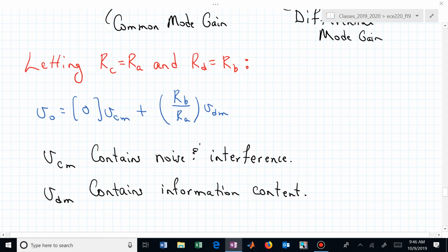The common mode, in general, if we had a sensor, or if you have been hooked up in the hospital, they may be measuring what your heart is doing. Well, you're picking up all sorts of noise on those wires, but they cancel them out. The common mode gets canceled out by putting them through a difference amplifier, or what could be improved upon and made an instrumentation amplifier.